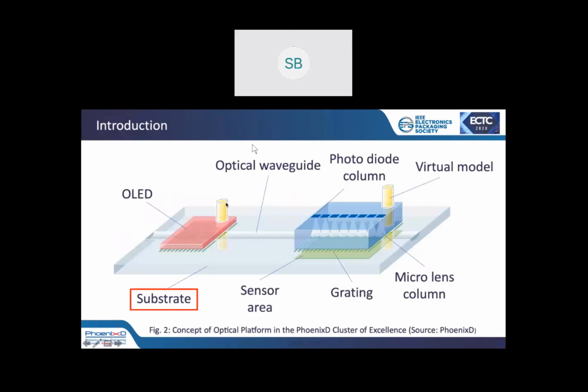We can see that there was a roughness difference depending on the temperature of the mold. At 130 degrees mold temperature, we can see the desired surface roughness of 30 nanometers. On the right image, we can see a picture from confocal microscopy as well, and you can see the channel of the waveguide. We measured all the channels on the bottom to see the surface quality of the waveguide top. We can see an increase of the surface roughness in the side walls, which is determined by the injection mold process.